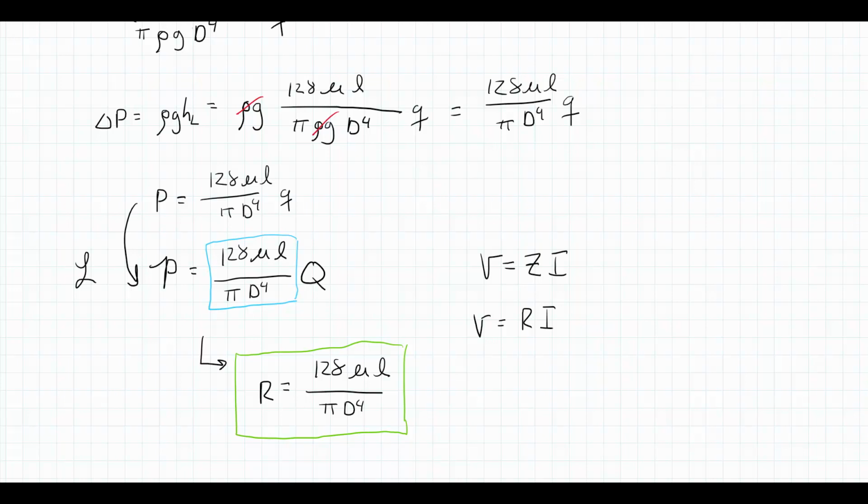So for large scale systems, we're not going to have to worry about modeling the resistance in the pipes themselves, but as that diameter shrinks, we get to smaller scale systems. Now the resistance through the pipes themselves, or the tubing itself, is going to be of concern to us, and we will want to include its resistance when we're making our model, and that's going to come into play when we are coming up with transfer functions.